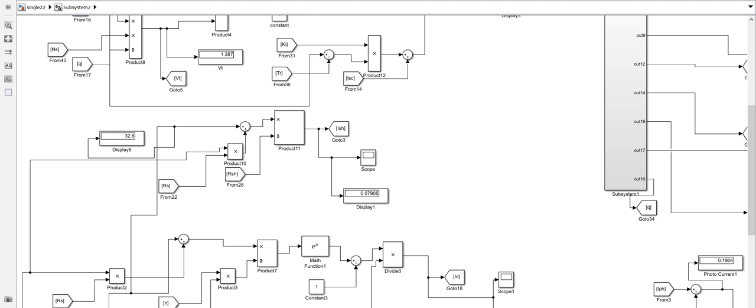And this is a single diode model, and we have to compare it with the double diode model. These single diode equations assume a constant value for the ideality factor, like we take an ideality factor n equal to 1.3, and in the double diode model we have to take it in a different way, like we use a1 equal to 1, a2 equal to 2, and some different equations come in. At high voltage, when recombination in the surface and bulk regions of the device is dominant, the ideality factor is close to 1 in the double diode model.